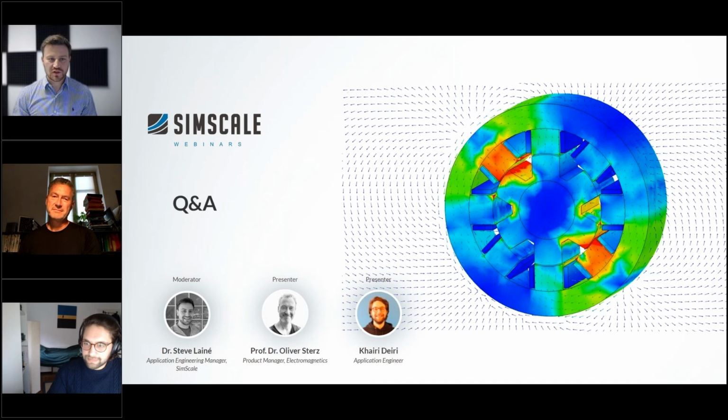I really like that demonstration because I think it shows what's possible with SimScale now that there are multiple physics available, including the electromagnetics. You can find out what the force would be and evaluate that in a structural analysis. Obviously, we didn't have time to cover everything today because you could also use Joule heating in a thermal analysis to look at how those electric currents heat up the whole assembly, and you could analyze the thermal properties as well. So it really does enable multiple physics for your designs.